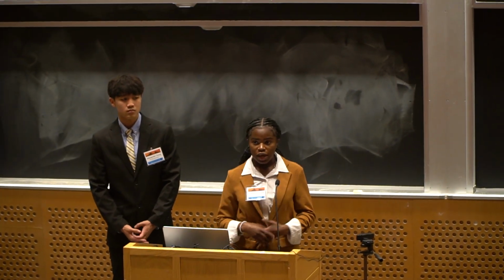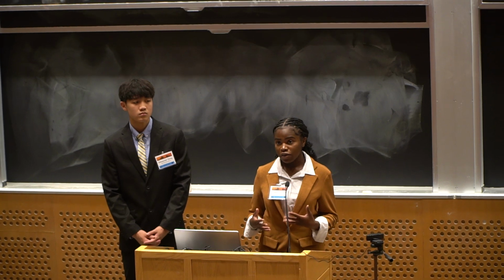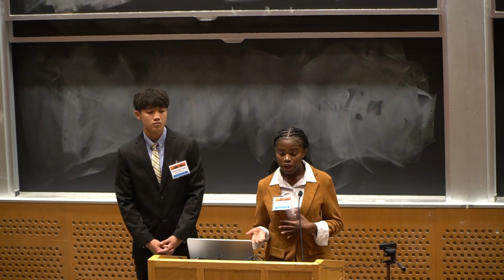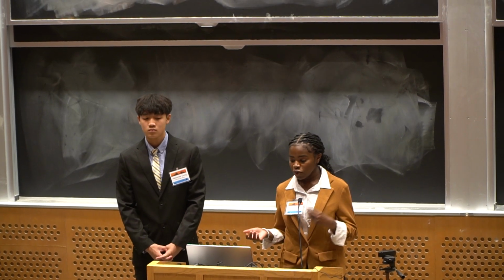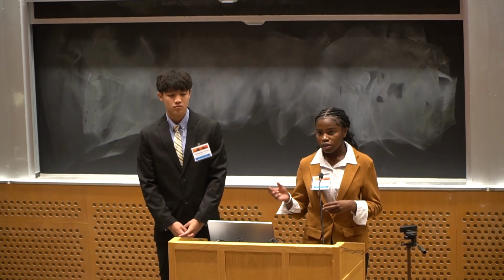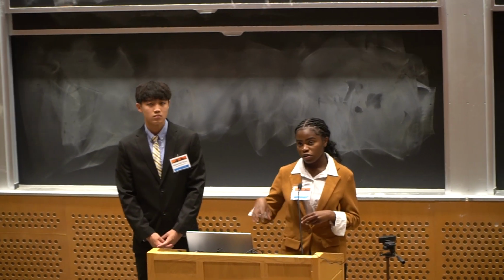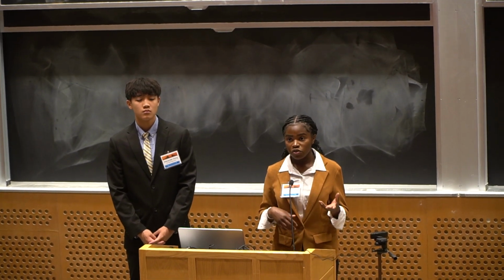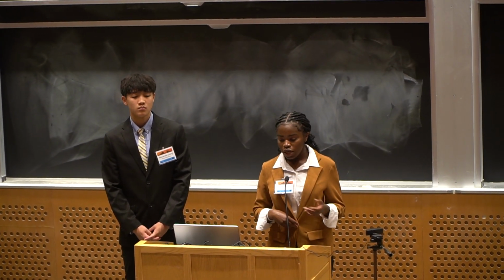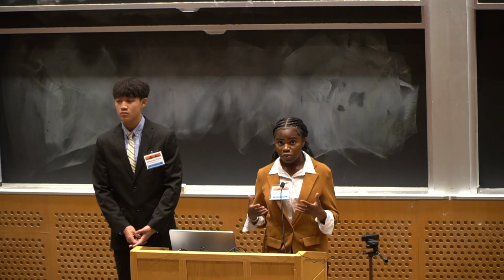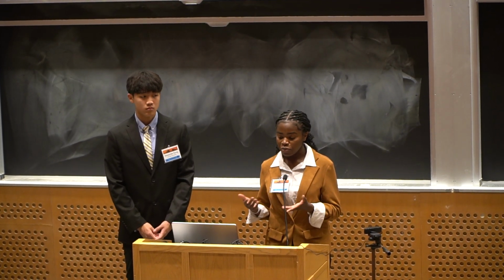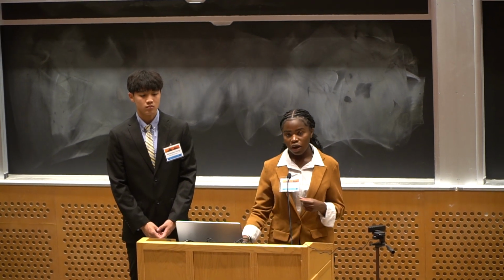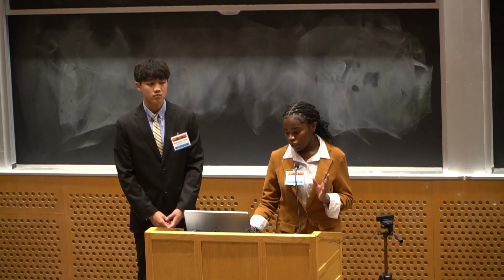So in order to determine the accuracy of the script's rho value calculation, we decided to conduct a distance accuracy test. And the basic setup for the test was connecting a camera to a Raspberry Pi and setting the tennis ball a distance away from it and increasing the distance in increments. And then we ran a script that would output the distances measured. And so at first when we ran this test, we didn't calibrate the focal length of the camera, and so we got undesirable results. After calibrating the focal length of the camera, we got more desirable results, which Karina will talk about in the next slide.